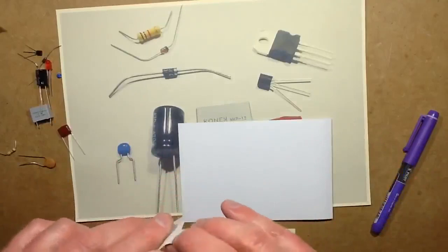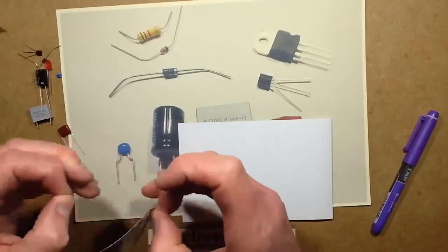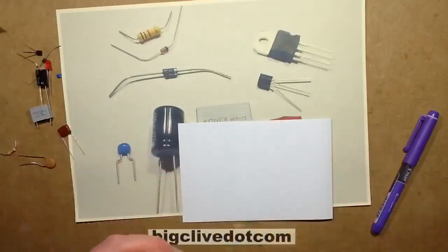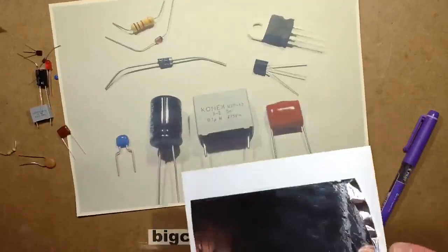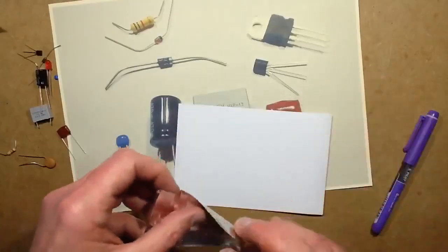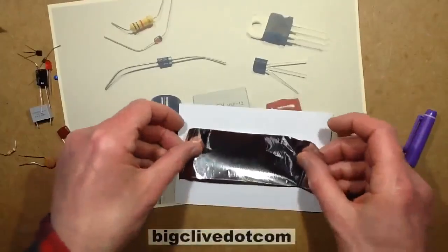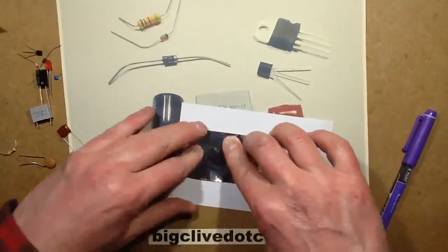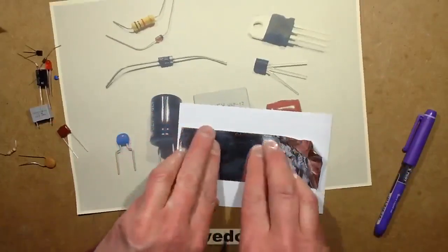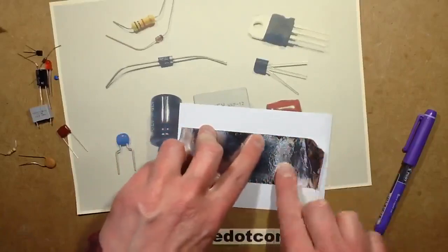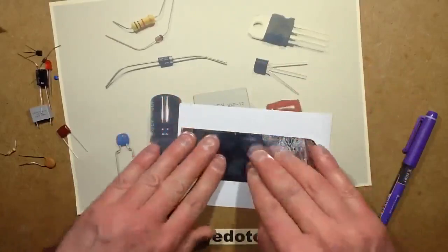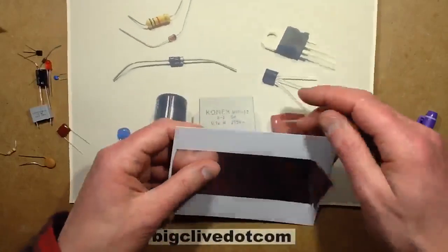And this is the physical construction that's used throughout all capacitors. They're all pretty much like this, but not using cardboard and aluminium foil. So let's get that pretty much as close to the other one's alignment as possible. And the 2 factors determining the capacitance here are the area of metallization that's in parallel with the other one, and how thick the insulator is in between.